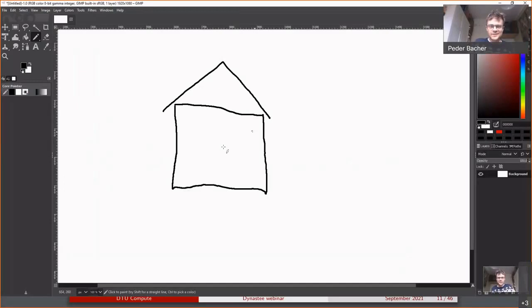That's a very simple building. Let's say we want to model the indoor air temperature here, and we will use the ambient or external temperature in the model. Let's say the model is very simple. We'll just represent the envelope of the building with a resistance and the thermal capacity of the building with a capacitor.